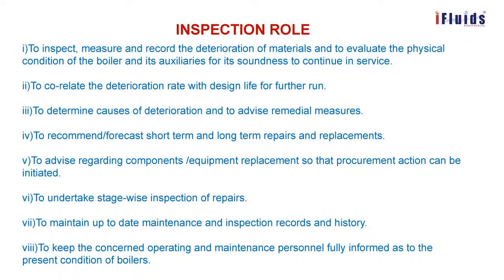The inspection role is to inspect, measure and record the deterioration of the materials, and to evaluate the physical condition of the boiler and its auxiliaries for continued service. It is also to correlate the deterioration rate with the design life for further run, to determine causes of deterioration and advise remedial measures, to recommend or forecast short-term and long-term repairs and replacements, and to advise regarding component and equipment replacement so that procurement action can be initiated.